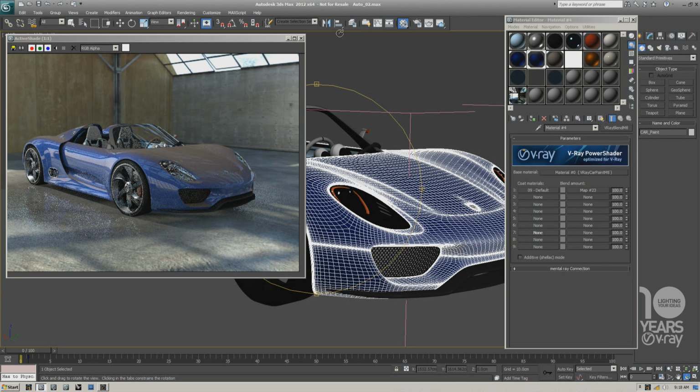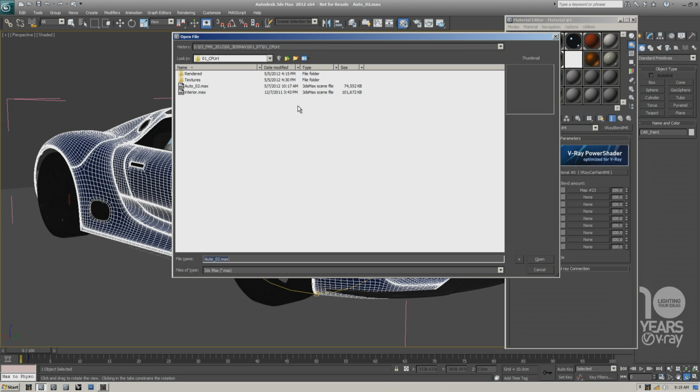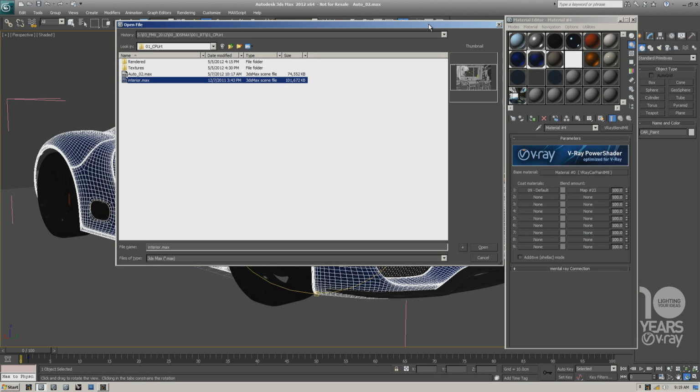Okay, so throughout this whole process, RT was helping me quite a bit. But keep in mind that every time you're dealing with a setup like this one, where you have an object surrounded by an HDR image, this is the easiest thing for a progressive path tracer to render. So these progressive path tracing engines render this type of images quite quickly. We can make it harder for V-Ray if we try to render an interior setup, for example, where light has to bounce a lot of times in order to illuminate the whole room.